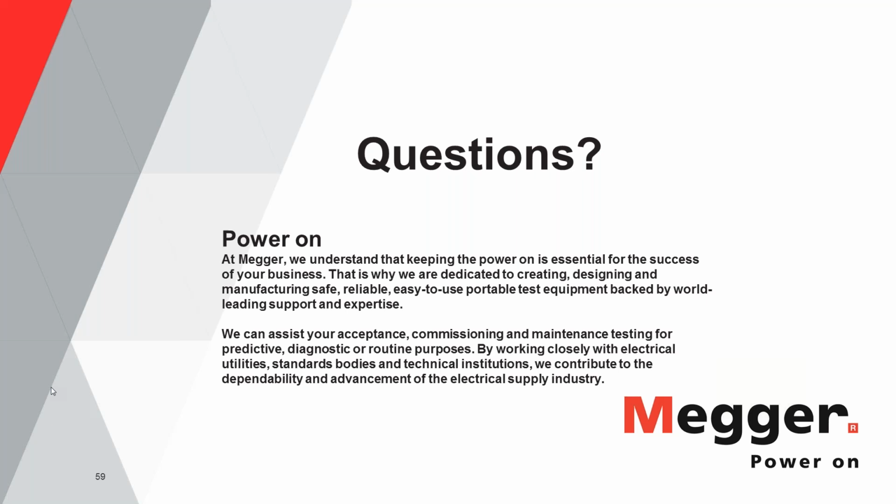It's not the same as instantaneous. As I just said, when you're dealing with short time characteristics, there is an intentional delay, however short it may be. But in instantaneous, the breaker is supposed to trip instantaneously as soon as the current reaches the pickup value. So these are two different things. The short time pickup is usually less than the instantaneous pickup. So the instantaneous pickup is set higher, because obviously if you want to introduce a delay on short time, then you don't want the breaker to trip at a current lower than the short time pickup.